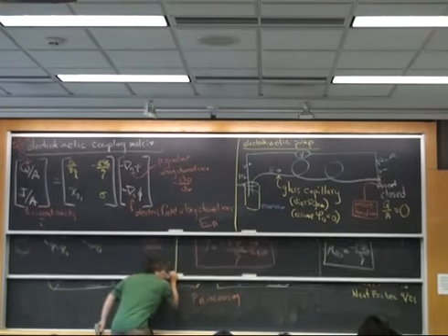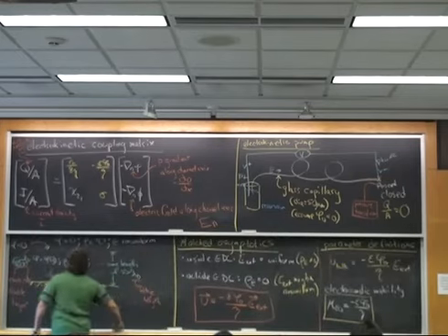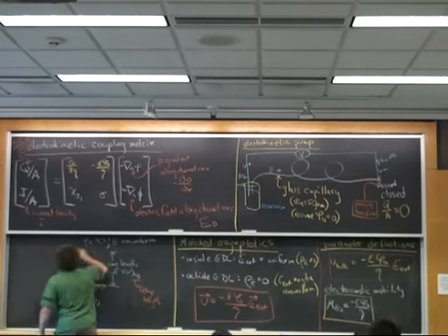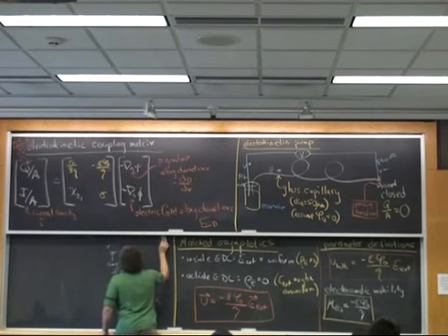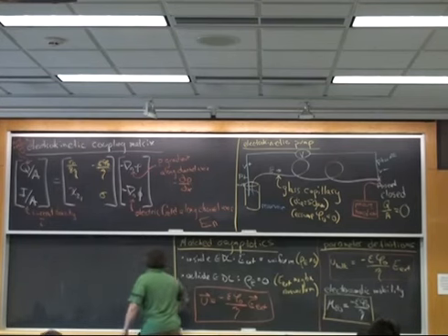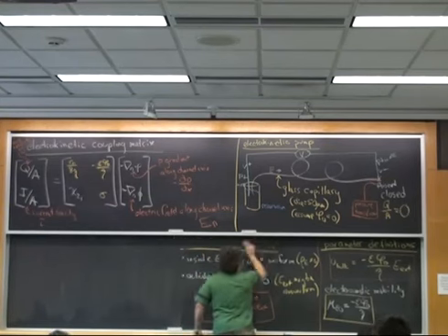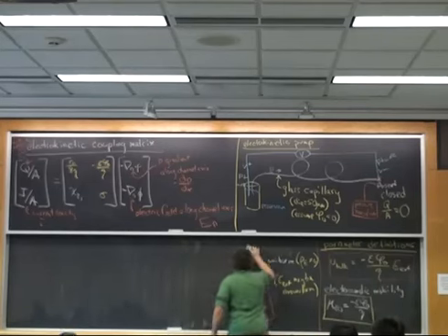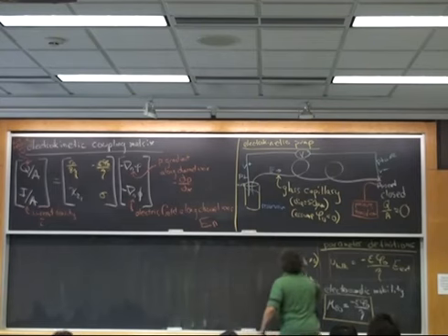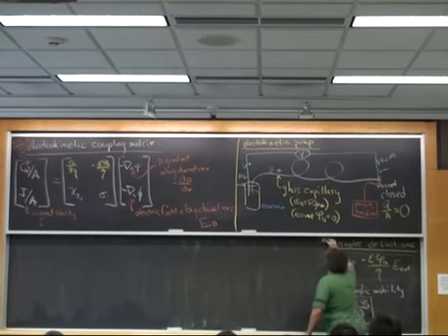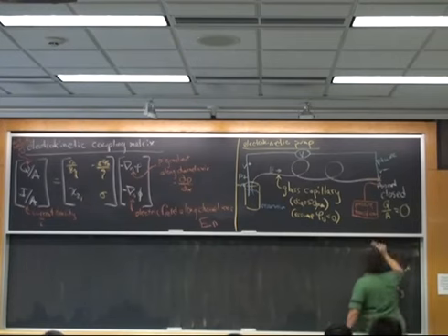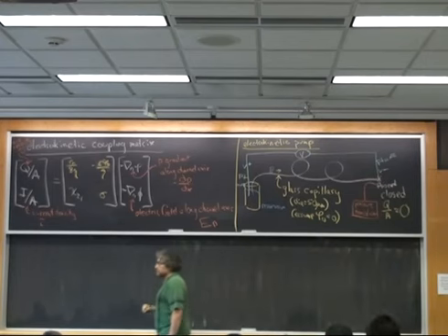Okay. Well, if I want to figure out how much pressure is generated, especially how much pressure is generated per volt, what's a sensible thing to do? Well, an easy thing to do would be to first solve for the velocity distribution, do an integral of that velocity distribution in space. That, by definition, will have an unknown parameter in it, which is the pressure gradient. Integrate all of that, say that that net volumetric flux has to be equal to 0. Solve that being equal to 0, and in so doing, one will find the pressure gradient.